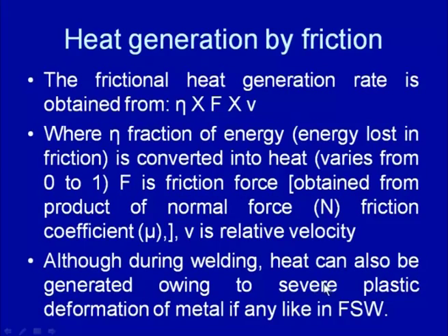So, this heat generation due to the plastic deformation, in addition to the heat generation by the frictional effect, both are taken into account while considering the effect of the frictional heat generation in welding processes like friction stir welding, and which help in the softening of the faying surfaces to develop the weld joint. So, these are the two other approaches which are used for generation of the heat, one by the frictional effect and another that we have discussed today.